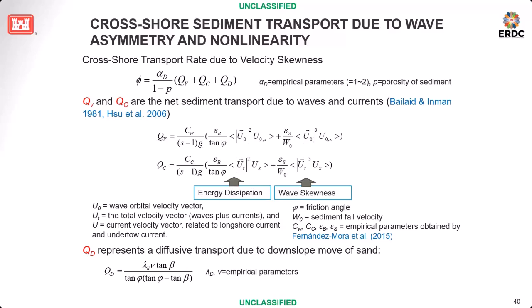Nonlinear wave contributes to this onshore and offshore change, but mostly those fair weather small waves provide net onshore change. But during the storm season, those high waves generate strong return flow that tends to take the beach sand away. So you have to have both mechanisms included in the model.